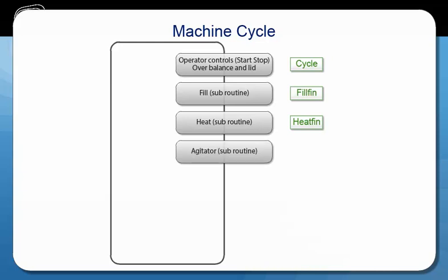The agitator cycle basically consists of the program for turning two outputs on and off in a fixed time cycle that was developed in the previous two videos. Refer to the two solutions suggested in the previous video regarding using counters in subroutines. When the agitator is finished, turn on the variable ag_fin.